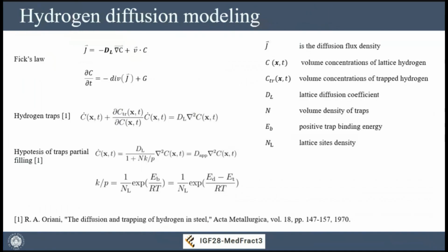So what we can do when we have to start dealing with hydrogen, first of all, we have to have an idea of how we can model the hydrogen diffusion in the material. The hydrogen diffusion in the material is governed by the well-known Fick's laws, where we need to understand and measure the apparent diffusivity coefficient, so the coefficient that is multiplied with the gradient of the concentration for having an estimation